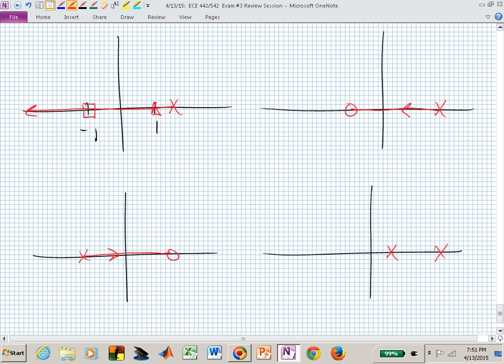To plus and minus infinity? Real infinity? I. Now they're going, I. Now they're going up and down, aren't they? Plus and minus 90. And where do these two meet? In this, because you have two isolated poles, no other poles and zeros, they are going to meet exactly halfway between. You don't even have to calculate the relative max. You know it's going right between.